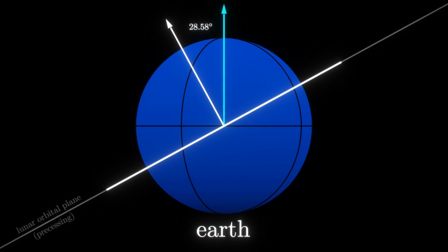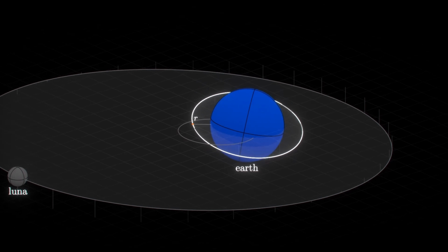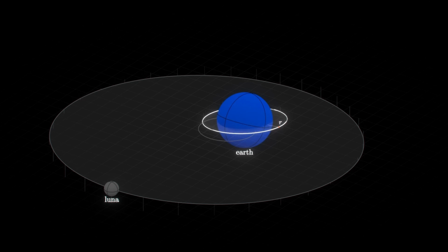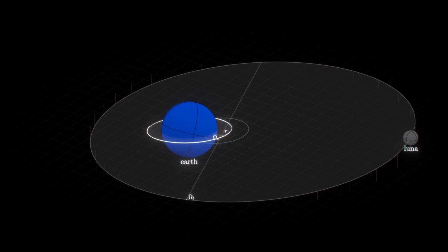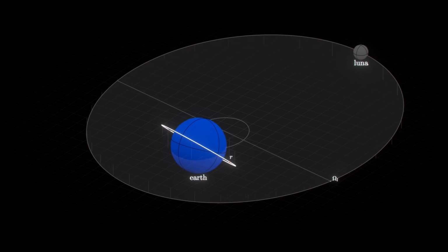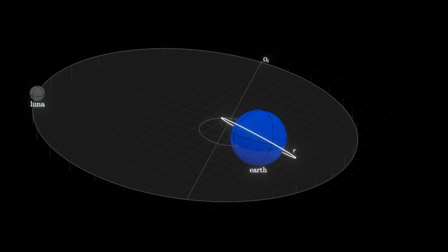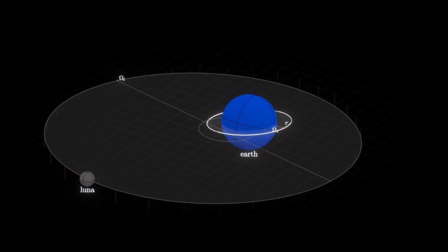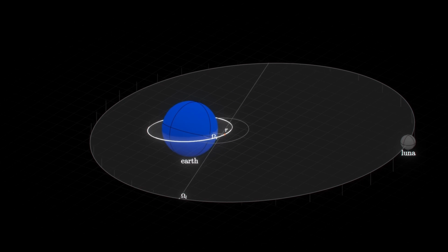But there is one more problem worth talking about first. Altitude also controls nodal precession and sets how fast the station's orbital plane naturally rotates around Earth. An exact 1,200 kilometer orbit would still work, but its precession would not line up cleanly with the lunar nodal cycle, so instead of treating 1,200 kilometers as an exact target, we treat it as the goal to aim for, and we search nearby altitudes for one whose nodal precession has a clean integer relationship with the moon's 18.6-year nodal